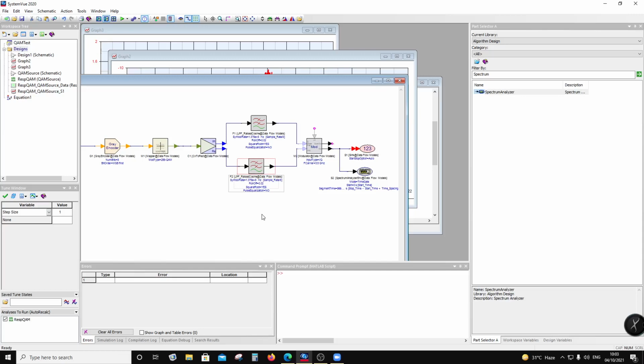So in 4G you used to have all the subchannels to be orthogonal, but in massive MIMO, because of the huge number of channels, statistically the correlation effects are less, so you can relax the orthogonality, and that's why the channel capacity of 5G is much more than that of 4G. That's the basic difference between 5G and 4G. So we are going to explore that later on in the subsequent sessions.